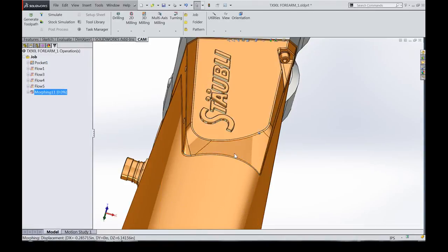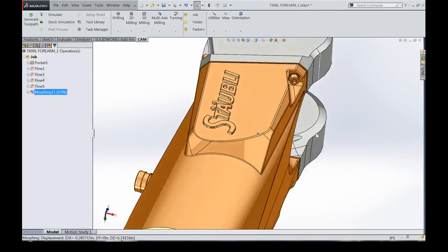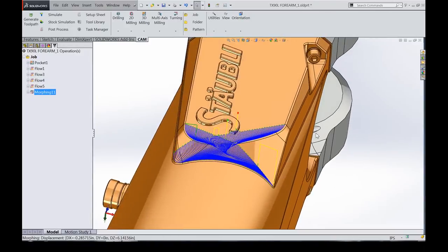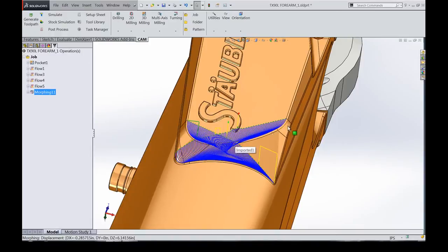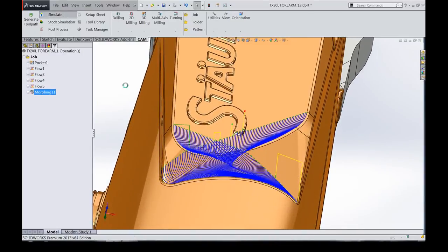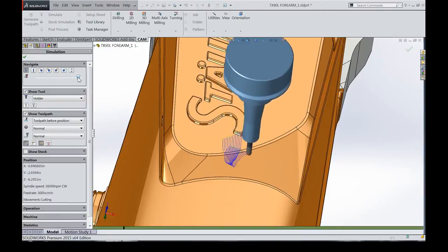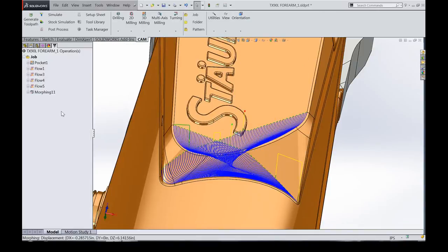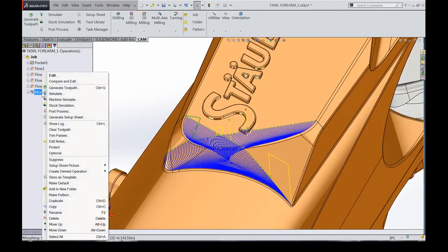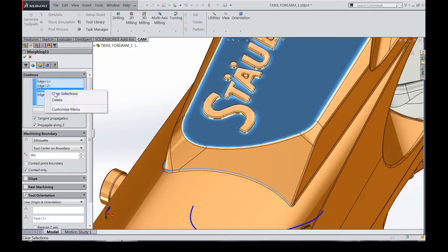No, let's just look at it. Oh, I forgot to add in a step over. Check use step over, there we go. We'll go into some of those details a little bit more later, but yeah, you can see totally useless, right? Completely garbage toolpath. I wonder what this even looks like when you simulate it. It's certainly not going to be, look at that, that's horrible. Completely the opposite of what we're looking for, and certainly the reason probably half of the people who hate this toolpath hate it. Okay, so let's simply correct that, but we'll look at some of the other issues.